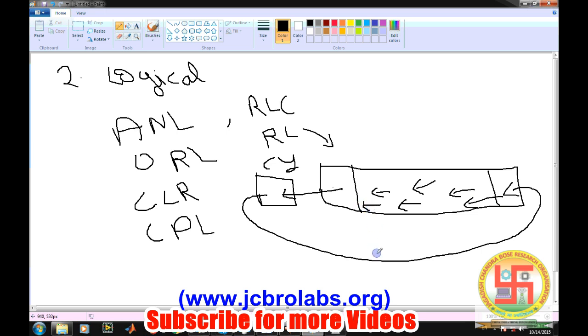So this is rotate left through carry. Similarly, we have rotate right. It's just the opposite of this one. The first bit will go to the end and all the bits will shift to the right side. Similarly, RRC, rotate right through carry. Same case, just opposite to RLC.